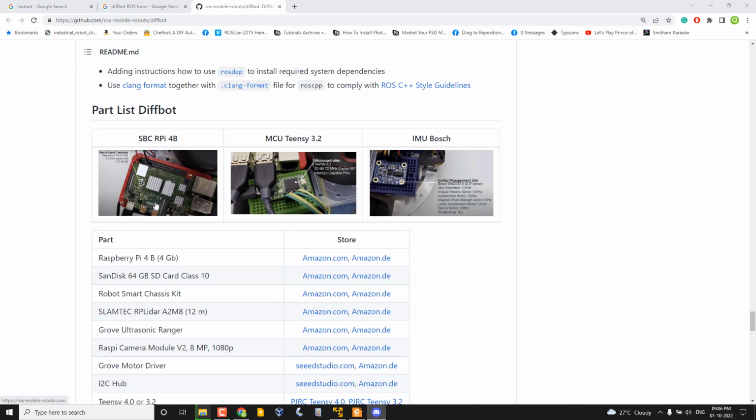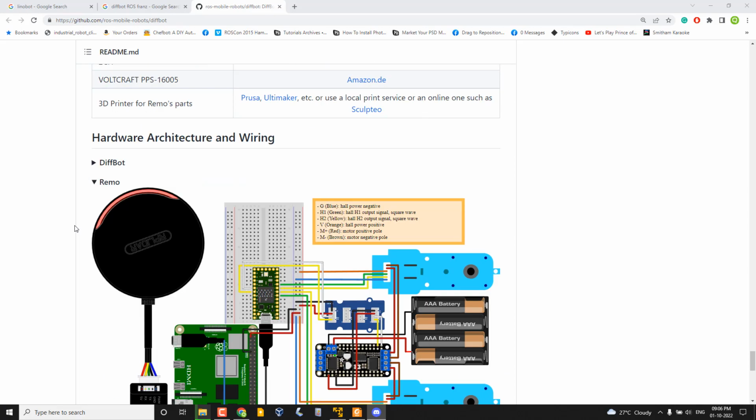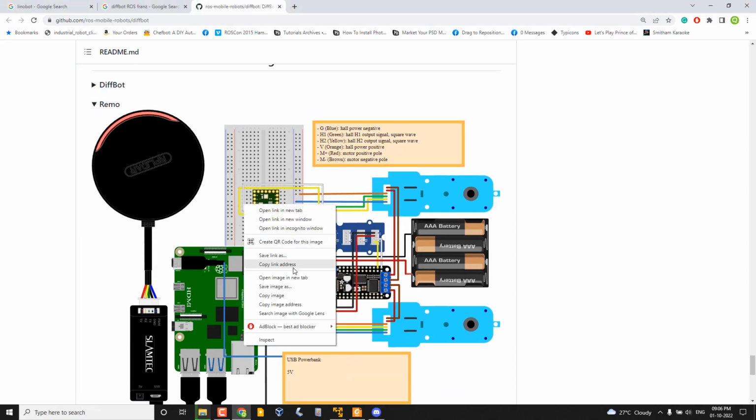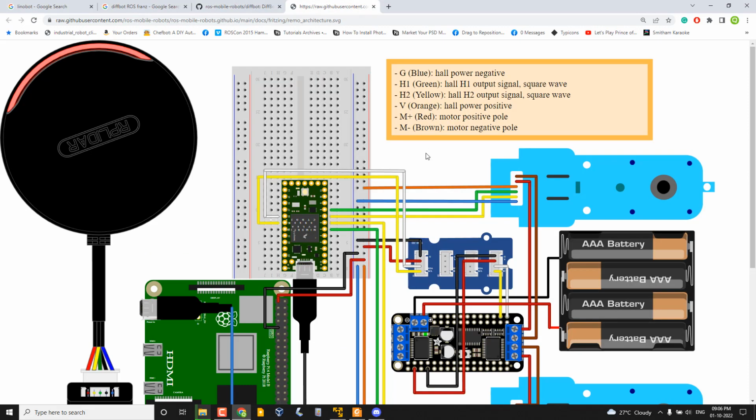For the A to B autonomous navigation, he used ROS on a Raspberry Pi 4, where he installed Ubuntu and ROS 1. He interfaced sensors like LiDAR there, because that can't be interfaced into a microcontroller.